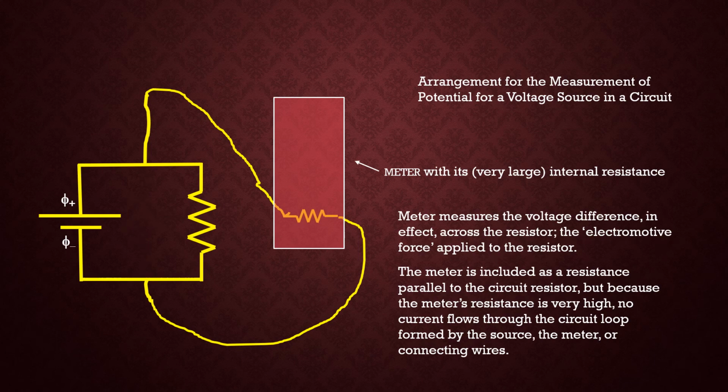I can, however, measure the voltage of a circuit in which current is flowing, but it involves measuring the voltage difference across the device. So in this particular case, I have current running through the resistor. The resistor is causing a voltage drop, in other words, a non-short circuit, you can think of it in terms of that.